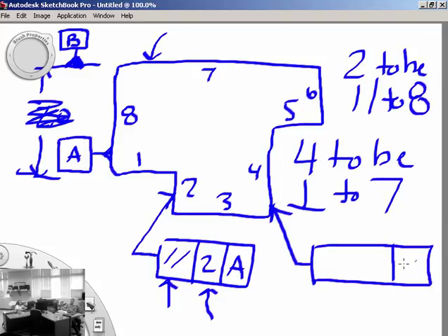I need to put what in this box right here? B. What's my size? 2. And what's my symbol here? Perpendicularity, and we're golden. So, straightforward process. Now let's do another one real quick.